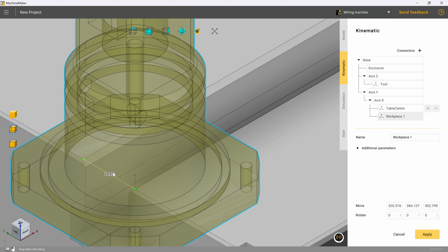And the best way of being able to move this workpiece coordinate into the center of that, instead of dividing 19.05 by 2 in a calculator and then adding it to the coordinate value that you've got here and all that sort of noise, you can actually write math functions straight into the coordinate box.